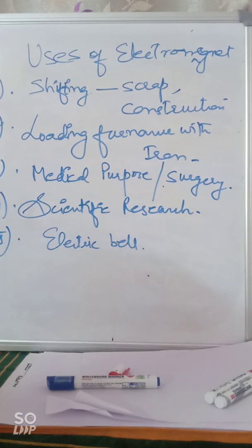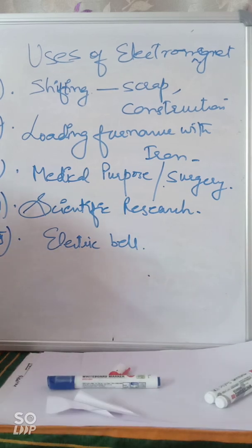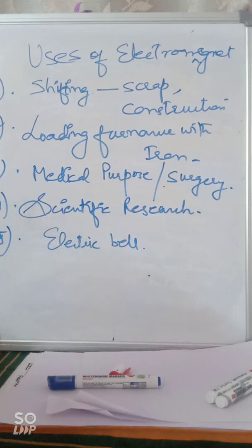They simply ask what sort of magnet is used: a U-shaped or horseshoe electromagnet. Which material is used? Soft iron. Why? Because of its retentive properties, because it gets magnetized and demagnetized easily.